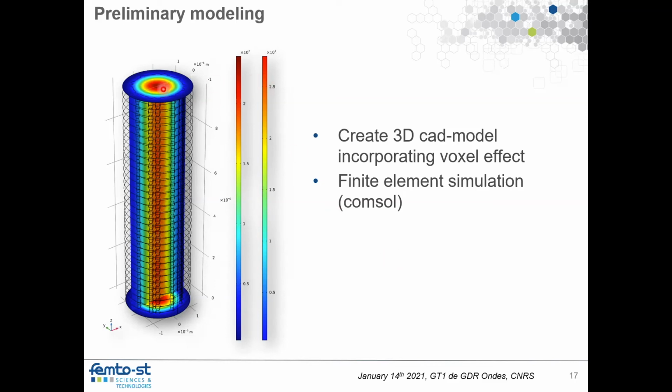So based on a 3D CAD program, we approximate or we model the 3D volumetric structure of our waveguides. And you can see here for a few examples, essentially what we do is we stack these 3D voxels where they overlap. They are basically Boolean combined in an OR operation. And then we have the rugged surface of these waveguides, and then using finite element simulations through COMSOL, we have essentially now started the simulation of these structures. And that is the current starting point.